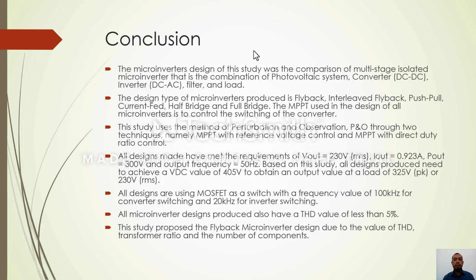All designs use MOSFET as a switch with a frequency of 100 kHz for converter switching and 20 kHz for inverter switching. All microinverter designs produced also have a THD value of less than 5%. This study proposed the flyback microinverter design due to the value of THD, transformer ratio, and the number of components.